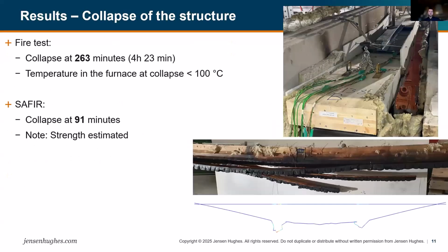So this is the main result of the fire test and the SAFIR modeling: collapse of the structure. In the fire test, we had collapse at 263 minutes, so almost 4.5 hours, which is almost 4 hours after the start of the cooling phase.